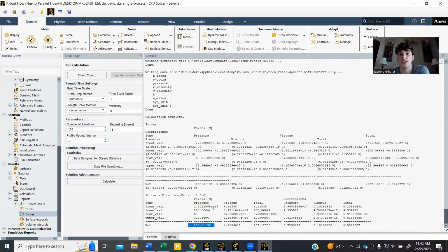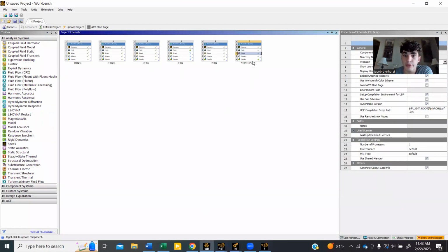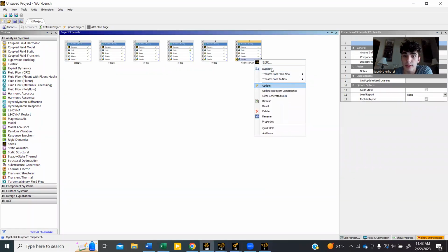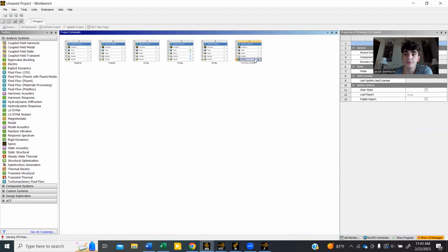Because the angle of attack has changed, you will see your drag forces will increase a lot. Now, when you look at your viscous forces, they are lower here. That also follows suit because the skin drag is inversely proportional to the pressure drag. So that looks good. That is all we really need for this setup. Now we can open the results and check our contours.